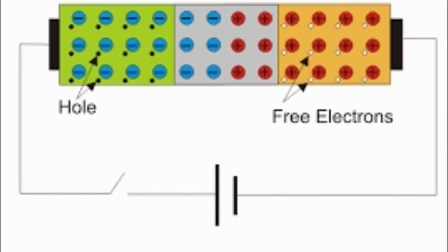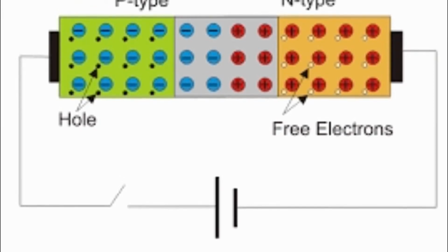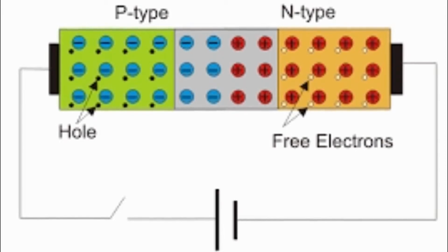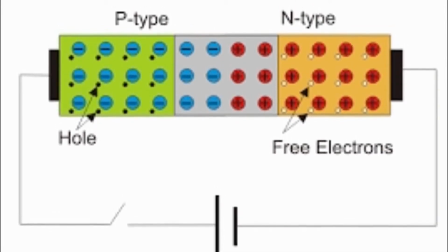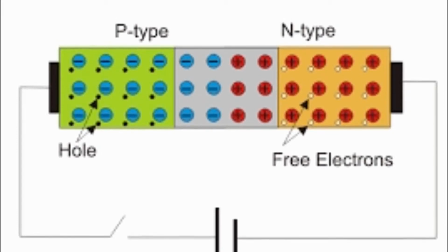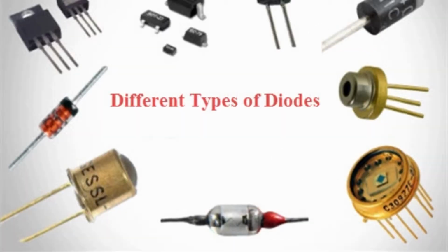The off state of a diode is achieved by reverse biasing, which means that positive or higher potential is applied to the cathode and negative or lower potential is applied at the anode of the diode. In other words, the off state of the diode has the applied current in the opposite direction of the arrowhead.